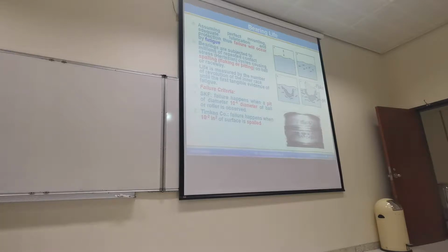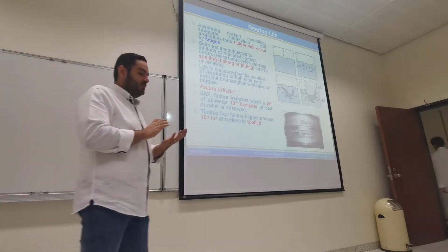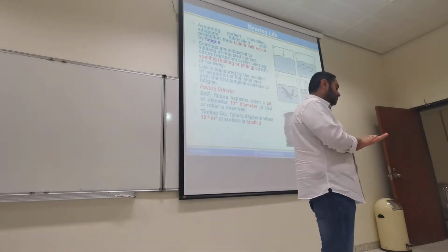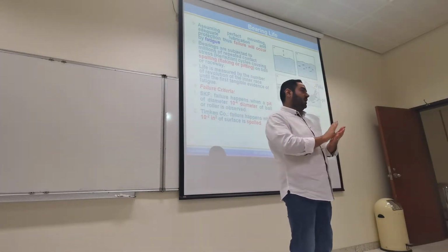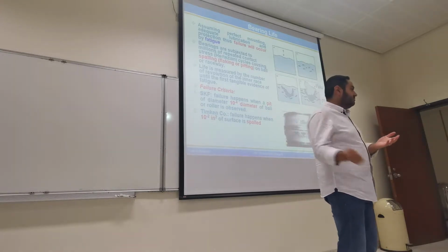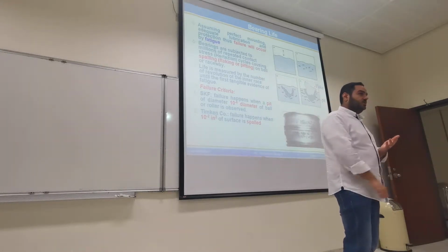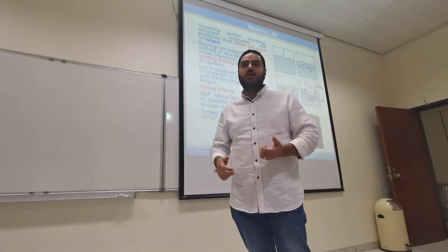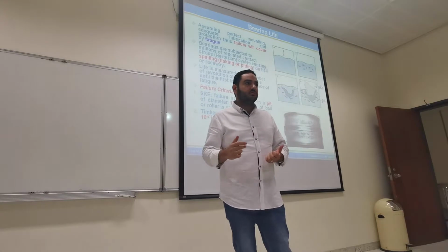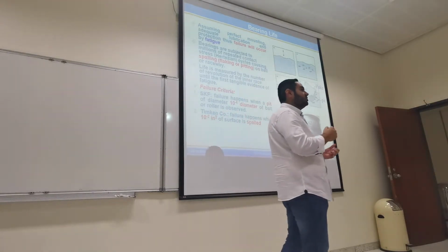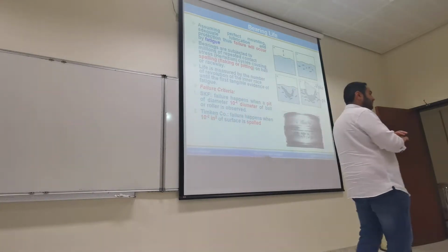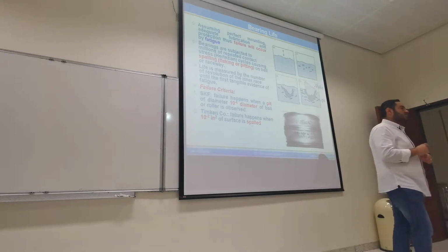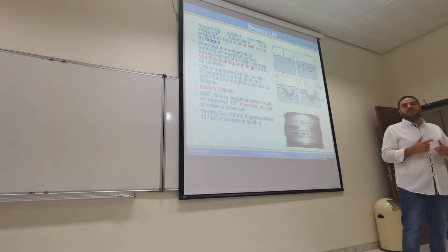There are a number of problems that may take place and cause failure in bearings. But if we assume that we are mounting the bearing correctly, so we're not hammering the bearing to get it to fit inside, we are not overheating the bearing to do shrink fit, okay? All of these things, and we're having sufficient lubrication inside the bearing. If all of these are correct, the bearings would fail under fatigue. So it is simply a fatigue issue.